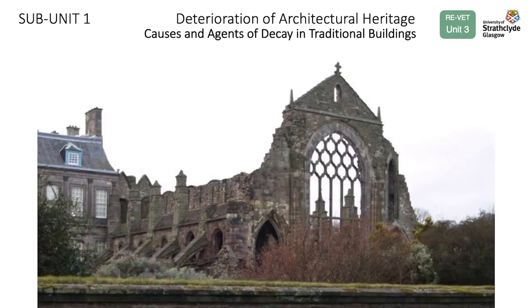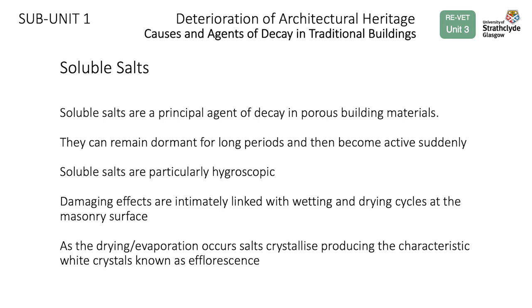The case of ruins is even more challenging, as water infiltration from exposed wall heads is more severe. Water mobilizes soluble salts, which are a principal agent of decay in porous building materials. They can remain dormant for long periods and then become active suddenly. Soluble salts are particularly hygroscopic. Their damaging effects are intimately linked with wetting and drying cycles at the masonry surface. As the drying evaporation occurs, salts crystallize, producing the characteristic white crystals known as efflorescence.